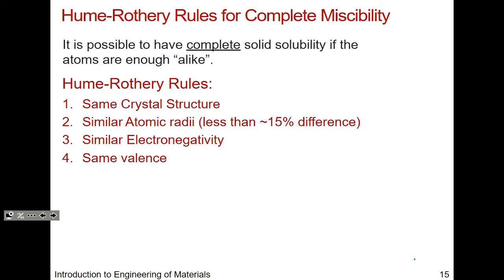So then we continue and say, okay, well, if we're not dealing with a single component, like the simple examples of just copper or just nickel having a vacancy, or self-interstitial where you move an atom to another non-crystallographic site. Okay, what happens when you have a second component? Sometimes it's an unwanted second component, whether it be a smaller atom or a same size atom. That's an impurity. Sometimes you want that because you're trying to engineer an alloy with say, higher yield strength, right? You're actually targeting some solid solution.